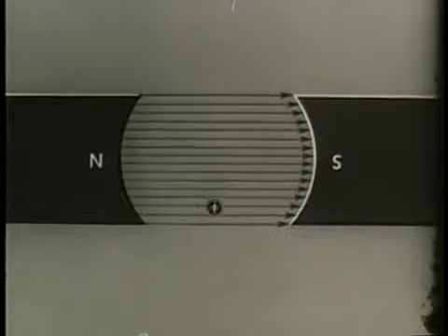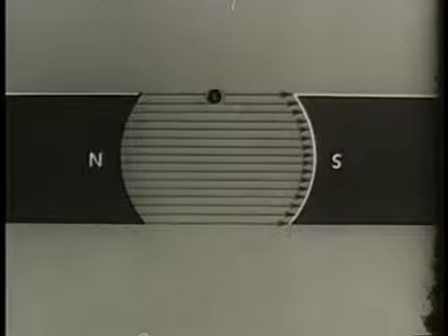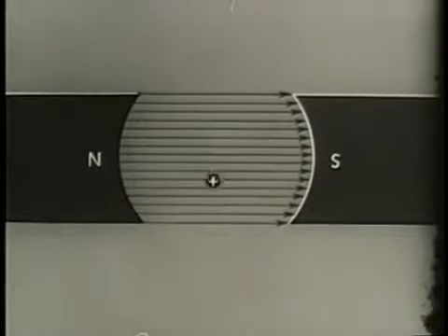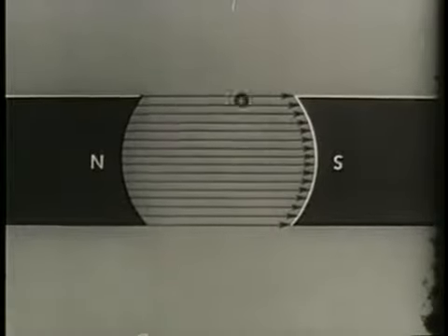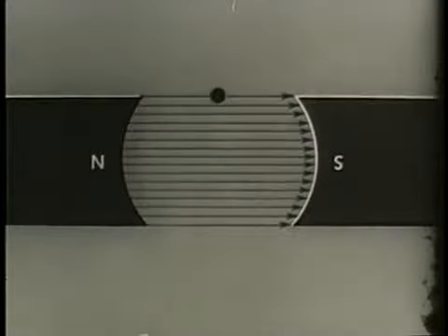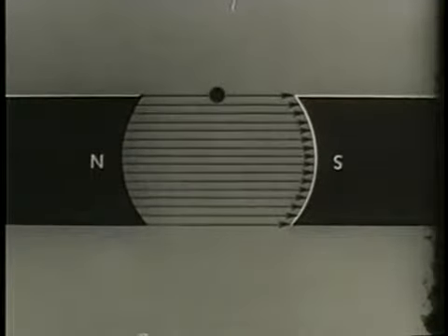This formula assumes conductor motion in a straight line, that is to say, cutting the same number of lines for each increment of its motion. But the conductor in an actual machine is not moving in a straight line, but rotating. When the conductor moves in a rotary path, the number of lines cut varies depending on the position of the conductor. At the top of the field, for instance, no lines are being cut and no EMF is generated.